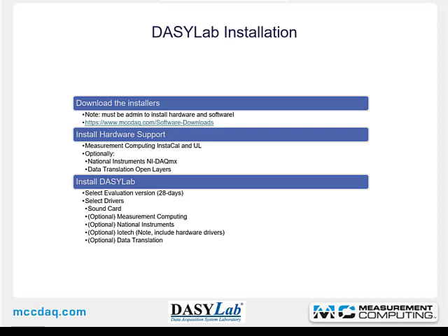When you install DASYLab, if you don't already have a licensed version, select the evaluation version. That will give you 28 days from the time you first run DASYLab. Select the drivers at the time of installation. The sound card is automatically selected, and you can choose Measurement Computing, National Instruments, the IoTech drivers, data translation drivers. You'll see that there are other drivers available. These are the drivers that Measurement Computing typically sees and supports.